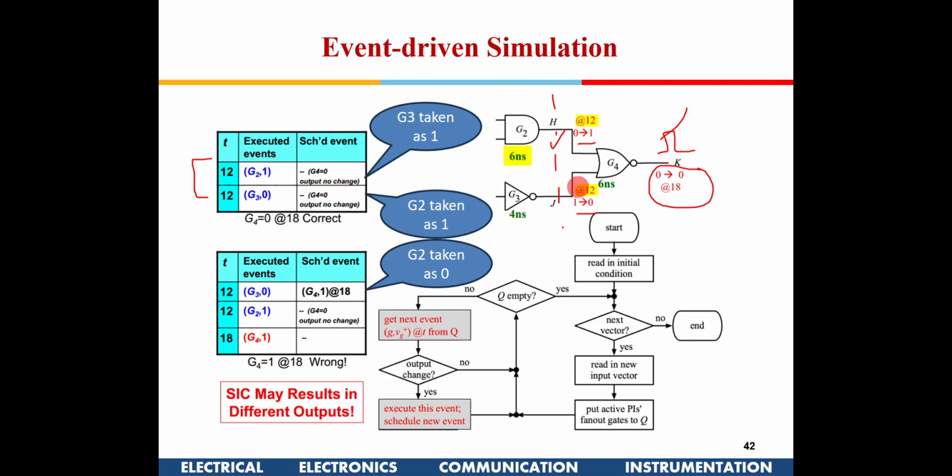When exactly two signals are coming to a gate at the exact same time, event driven simulation has no provision and doesn't automatically give any priority to either signal. It will just randomly pick one of them. And in such cases, there is a possibility that it might push out some glitch which may not be there in the actual circuit.